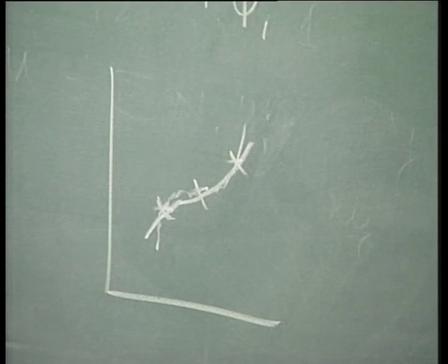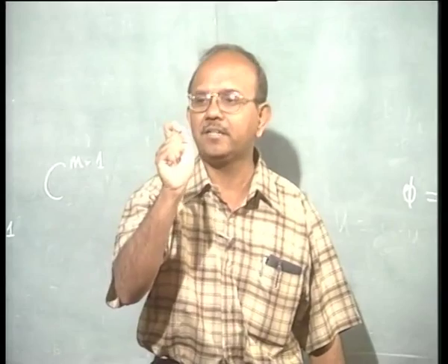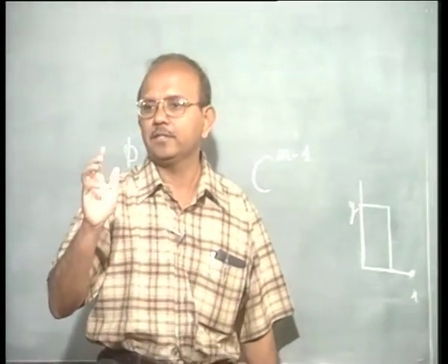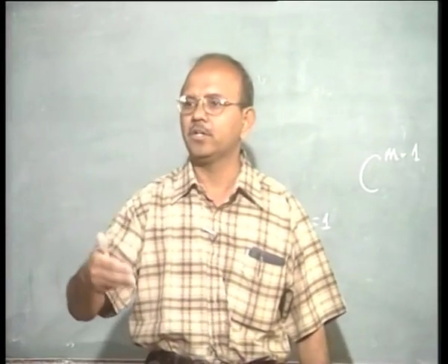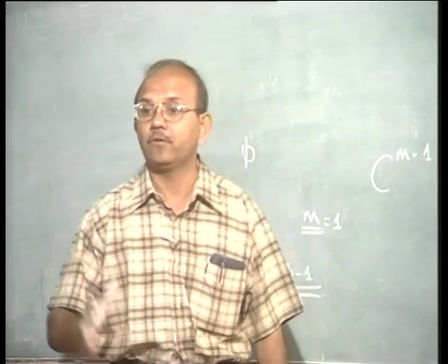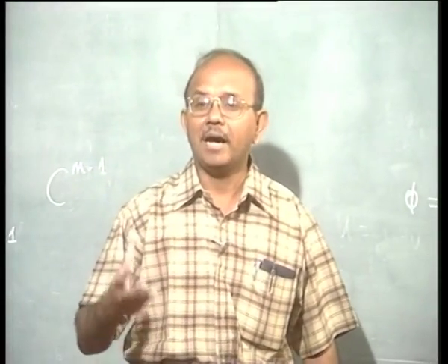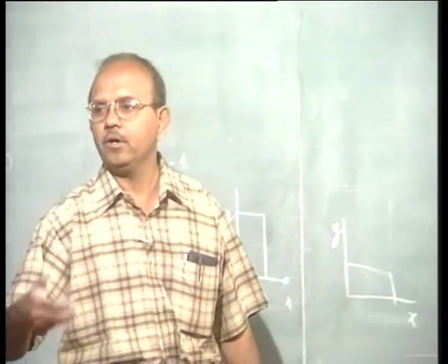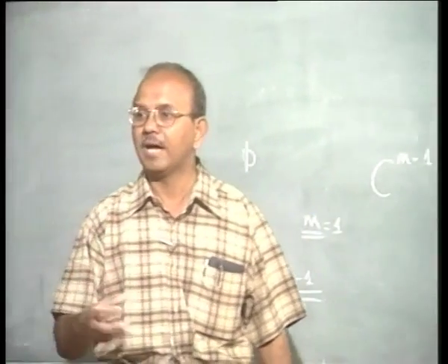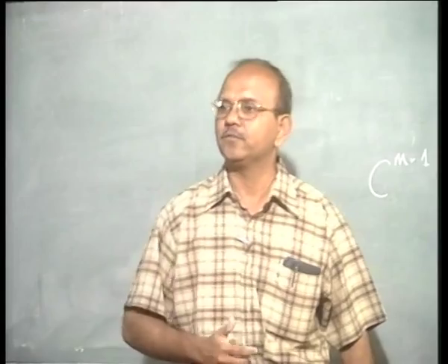C0, beautiful. So we are interested in C0 elements. I am not interested right now in continuity of the first derivative. For another problem, say when I go to beam problems, then I have to put continuity of the slope as well, so I will give that as one of the degrees of freedom.